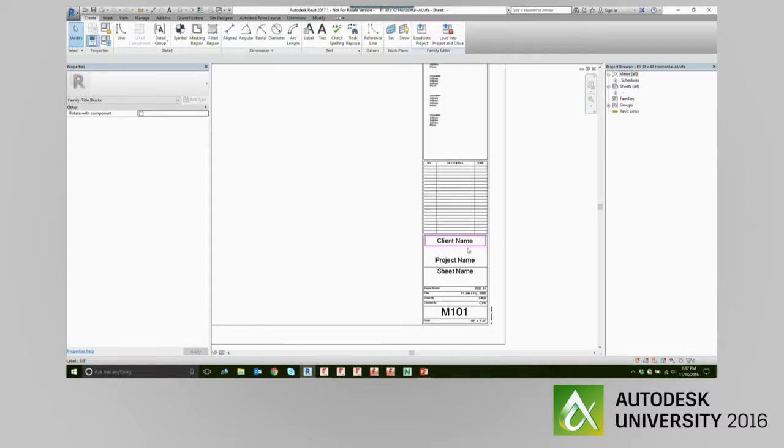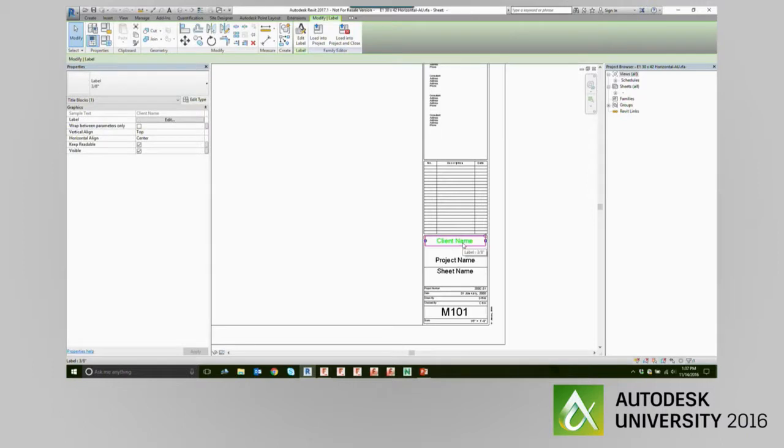The big difference in Revit templates is that we can take advantage of labels to populate our title block. Instead of using M-text or, in Fabrication, C-text and other ways to automatically populate information, with Revit we can use these labels. If you click on this, you can see it's a label. These labels represent bits of information within your project information or a family parameter, depending on what we're trying to report on.